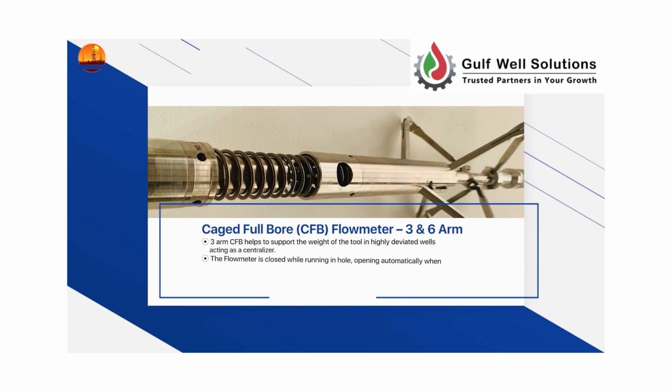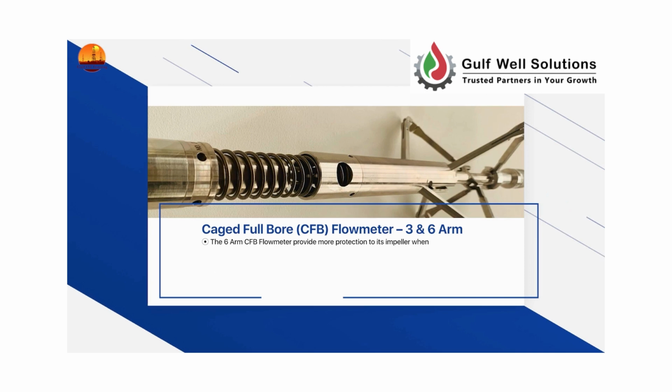The flowmeter is closed while running in hole, opening automatically when it leaves the tubing to enter the casing. The 6-arm CFB flowmeter provides more protection to its impeller when used in wells with large ID, gas lift mandrels, and in horizontal wells.